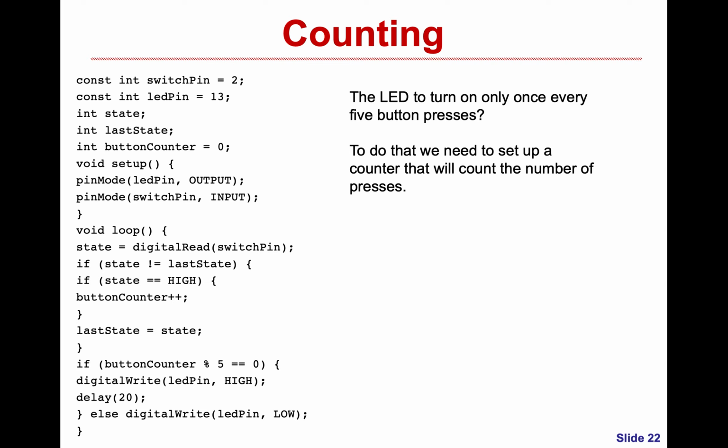If it is used as output, the digital write function will be used, and if it is used as input, we will use the digital read function. And we explained that in the case of input, we have 2 strategies to take. We can use the polling strategy, which we showed 2 examples of, or we can use the interrupt-driven strategy that we will explain in detail in later lectures.